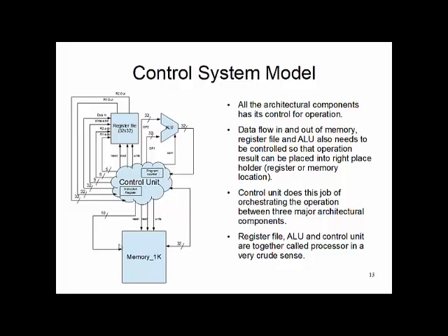It grabs it from some location in memory, during which the control unit issues that 10-bit address from the program counter to the memory system, and makes it a read operation. Of course, it keeps the reset operation ineffective, so that it does not wipe out the memory. So it takes care of that.